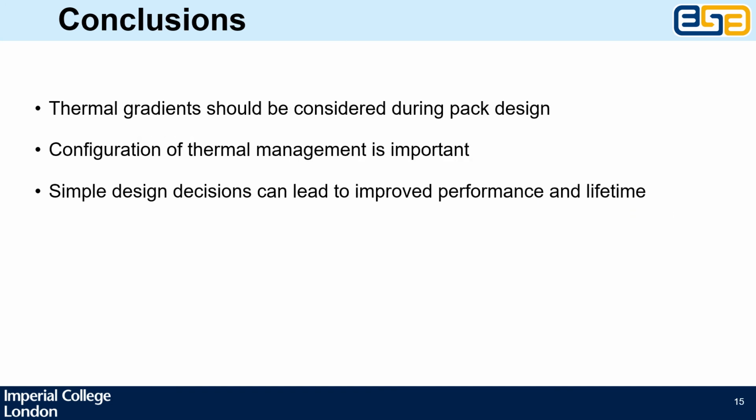In conclusion, thermal gradients can have a significant role in accelerating degradation of both cells and packs above the expected rate, and thermal management system design requires the consideration of any induced thermal gradient, as localized hotspots may lead to accelerated degradation in certain areas of the pack. During design of thermal management systems, designers should include considerations of how the thermal management system interacts with the pack given its topology, as it's possible to use the thermal management system to increase both the performance and lifetime of a battery.